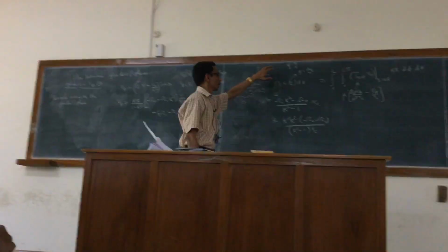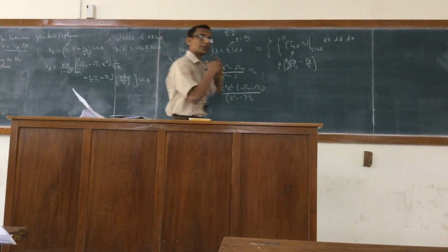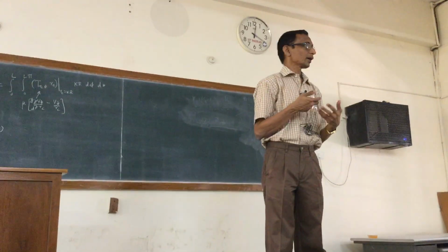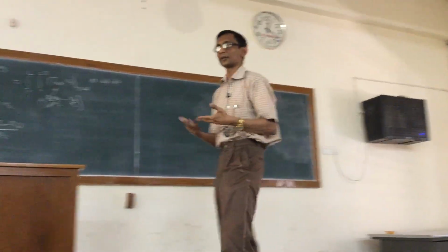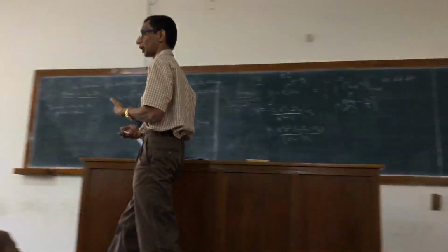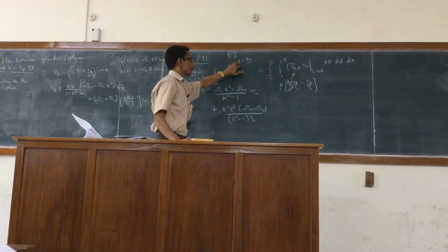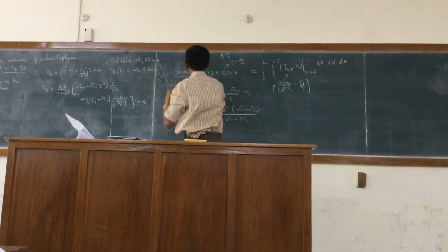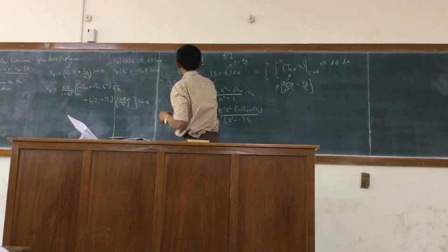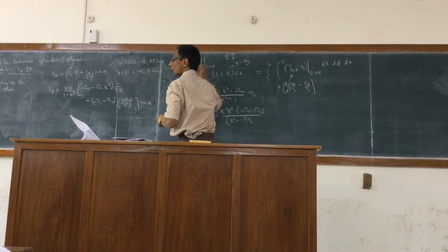I mean, I don't remember. And then you have to take the cross product of that with this. Right? And then everything will depend on ERC and E phi, and EZ. Those will all come into it, because you have to express the cross product of two vectors in cylindrical coordinates. We already have the formula. So I put a question mark on this, but what we want are the components. See, this is simply the Z component, or what we call the X3 component, of the torque.